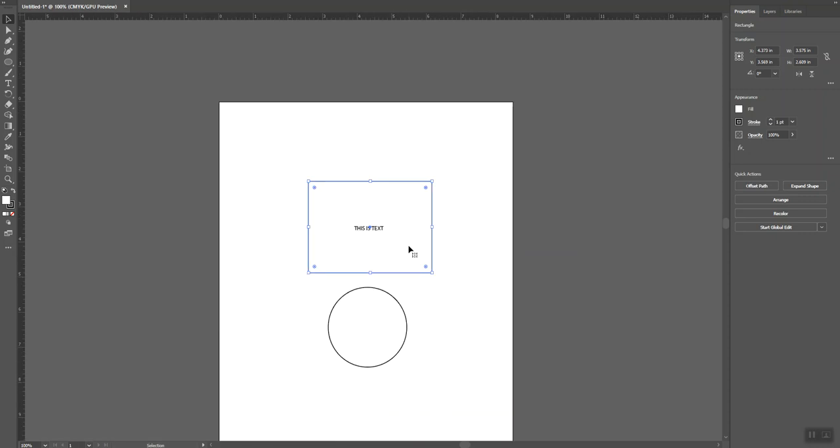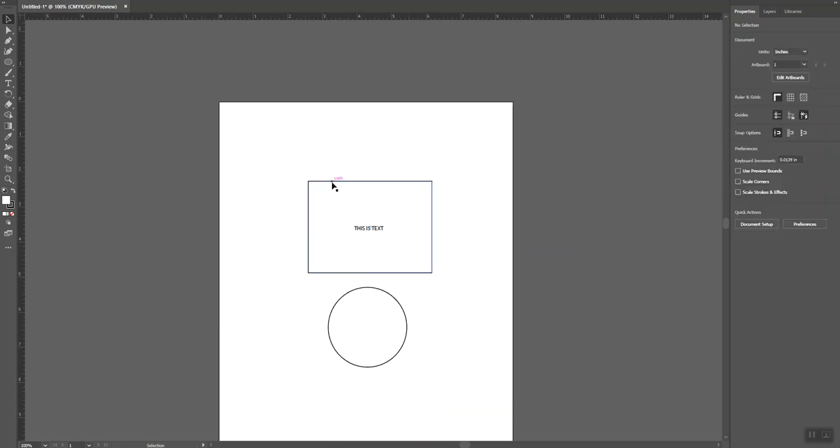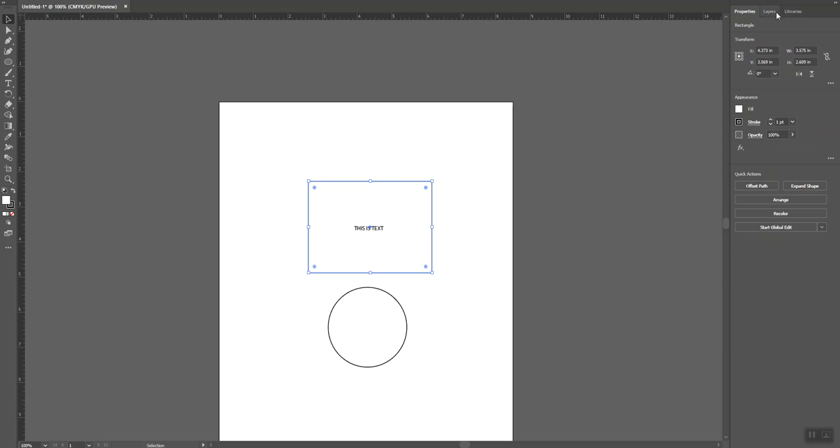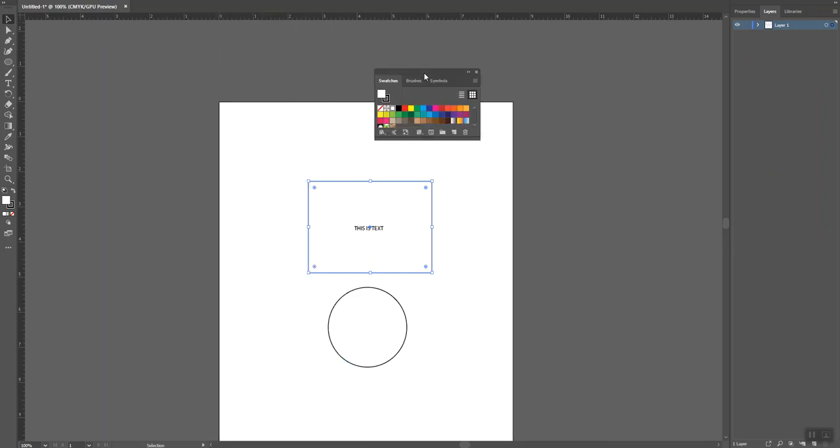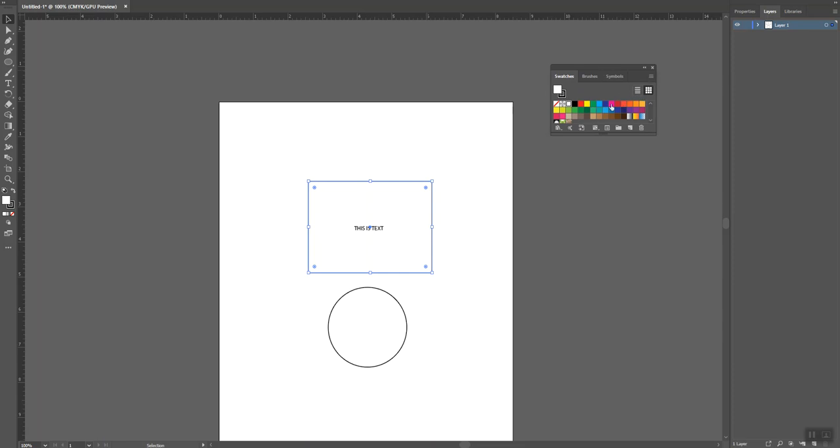The way it does that, it determines those two things by the color of the line and the weight of the line. So in this example, if we wanted to cut this rectangle out, we have to make sure that two conditions are present. And what I'm going to do is turn on my swatches here. Swatches are the colors. And we have to make sure that our colors are correct. So right now it's black. So anything that it sees as black will be basically engraved. This will go back and forth, engraving. Anything that it sees as red will be cut out.